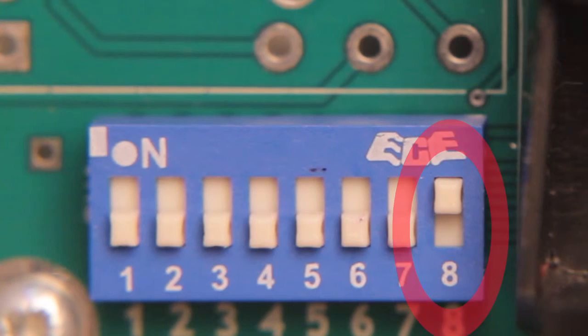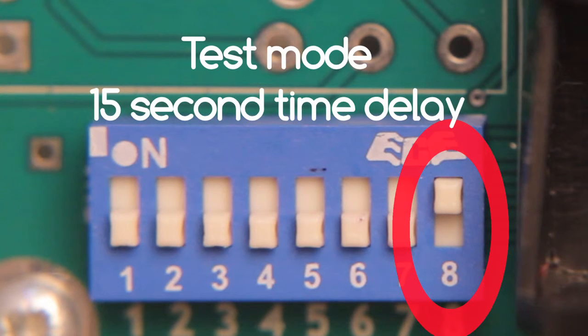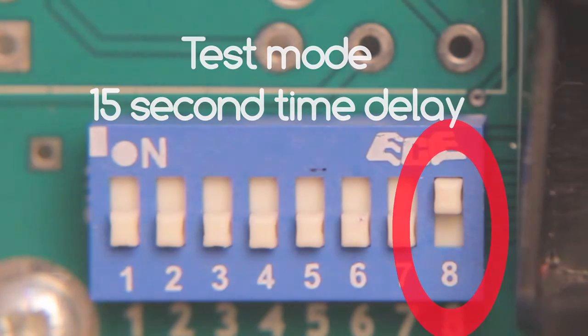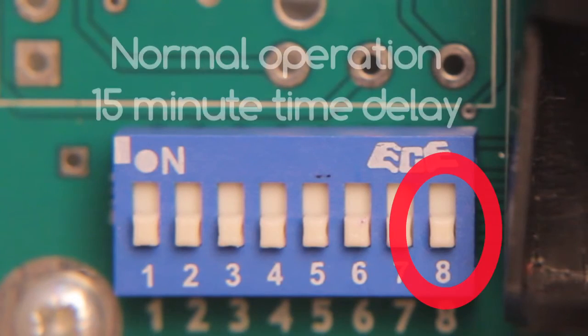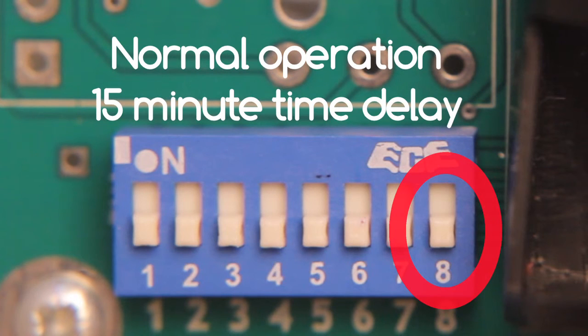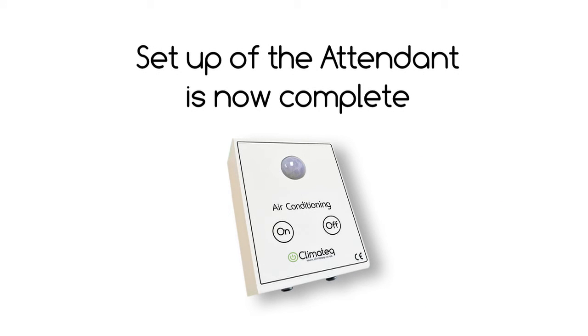Switch 8 is for test mode and normal operation. In the on position, the attendant is in test mode. This means there is only a 15-second time delay between the last movement and the signal to turn off. Once testing is complete, switch 8 can be moved to the off position for normal operation, which means there is now a 15-minute time delay. Setup of the attendant is now complete.